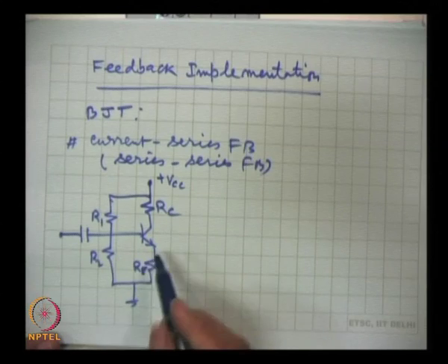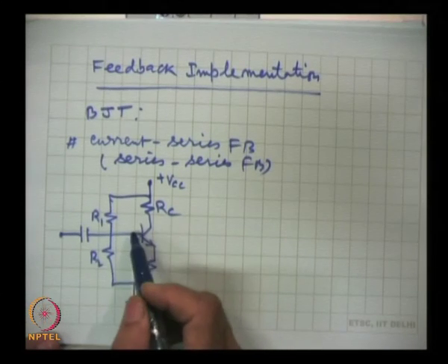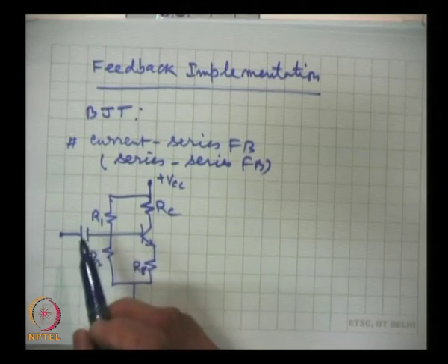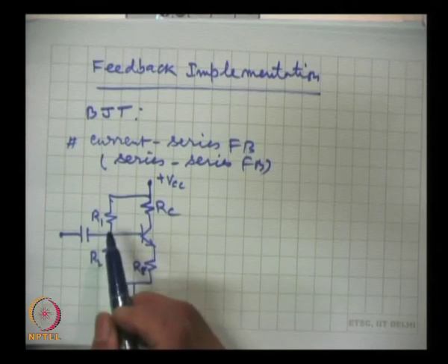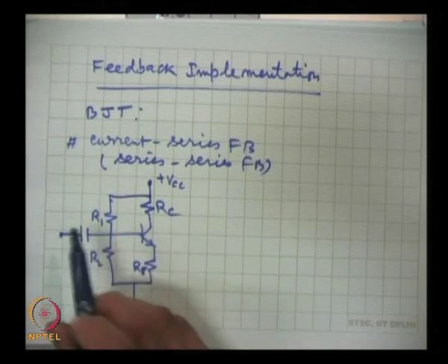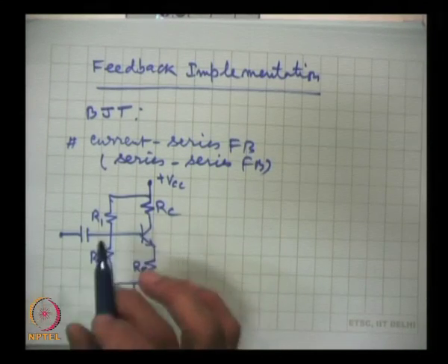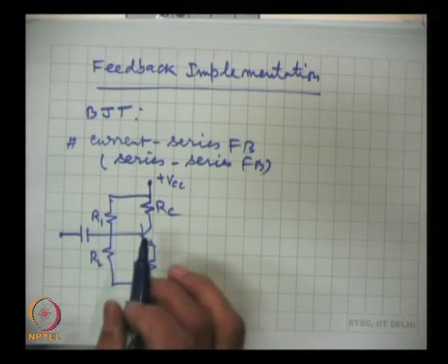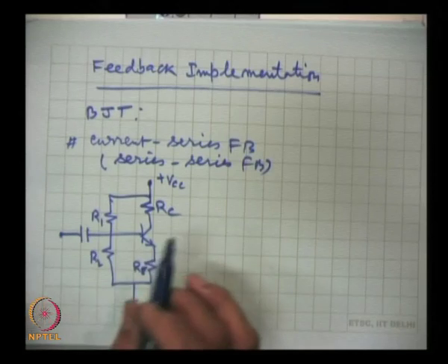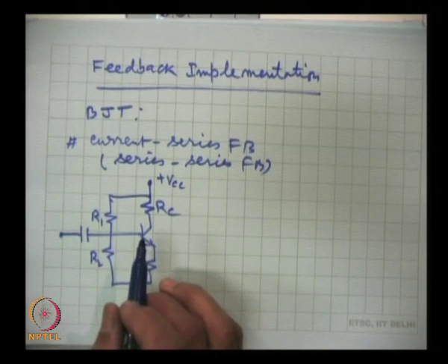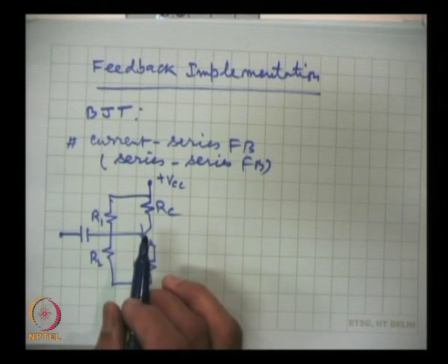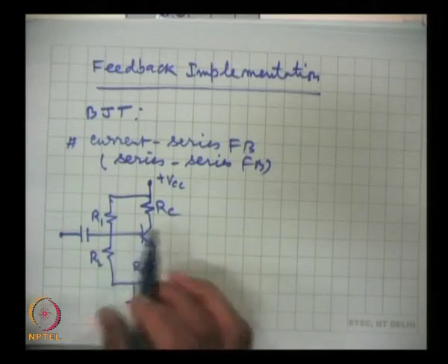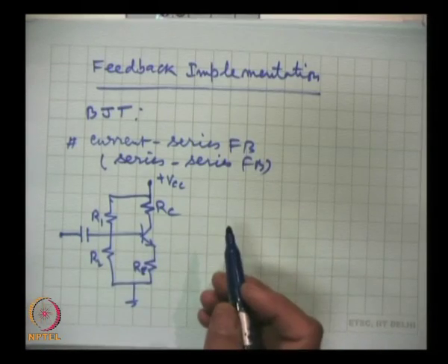of this resistance we have seen that the input is in no way connected to the output and the circuit is highly unstable. Any variations will be reflected immediately in change of the characteristics of the amplifier. For example, rise in temperature will enhance the gain, which is not desired.